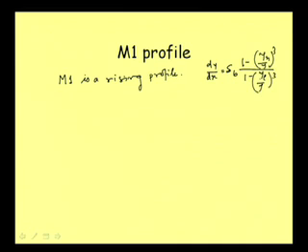Well, that is the equation, and in case of a mild profile, that is mild slope, our CDL line is here, NDL line is here. So it means that critical depth is this one, yc, normal depth is yn, and suppose the profile is here in zone 1 because it is M1.